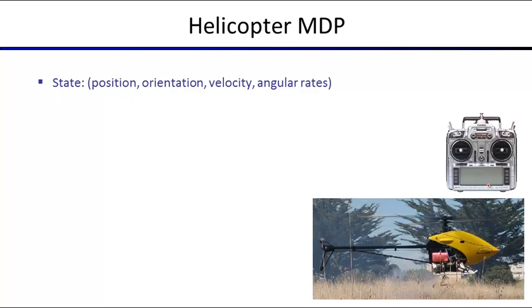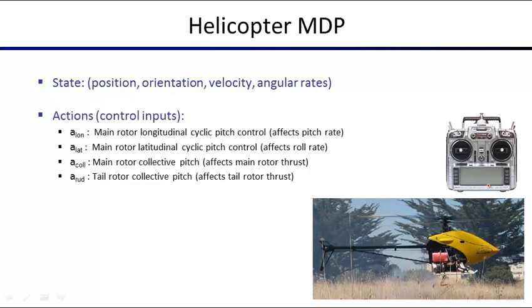The other thing you need to do is then to control it. You need to have a model for how it behaves and then send out controls. What control inputs do you have to a helicopter? How does that thing fly? It has blades going around. Depending on the angle of the blade, you push more air down or less air down. A very steep angle pushes more air down. And so the steeper the angle, the more air you push down, the more vertical thrust. That is your collective control, one of your control inputs.